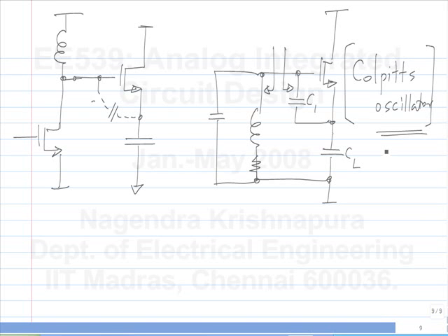It was a very popular oscillator. It is still, if you want to make discrete oscillators and so on. Now, with very low voltages in ICs, in CMOS ICs, you can make oscillators in a different way. That's why now you don't see as many Colpitt's oscillators anymore. The second thing is, the last class I talked about the importance of fully differential circuits. It's hard to make a fully differential version of a Colpitt's oscillator. But otherwise, it's a very popular oscillator.